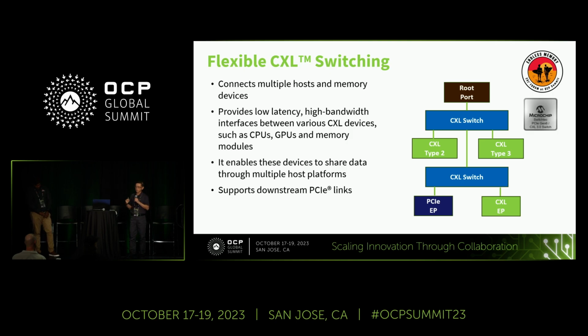Now, one thing I want to mention is that I think the previous presenter said it's going to be a highly complex system for PCIe Gen 6 because the encoding is PAM4 and not NRZ. So the previous generations, Gen 5, Gen 4, Gen 3, have different encoding, and now PAM4 adds one more complexity to the SerDes itself. But since we have already done many SerDes generations, we feel confident that we're going to have enabled this next generation SerDes coming up.